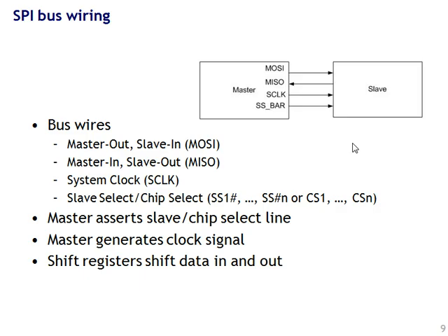You could use some kind of a mux or decoder, and then use a small number of bits to control a large number of slaves. In other words, if you had a 3 to 8 decoder, then you could use 3 bits, and only one slave would be selected at a time. Right? So 3 to 8 decoders guarantee that only one slave will be selected at a time if you had 8. Of course, you could have a 4 to 16 decoder or a 5 to 32 decoder, whatever you like. That'll save you a bunch of bits, but then you need an extra chip, right? The decoder.